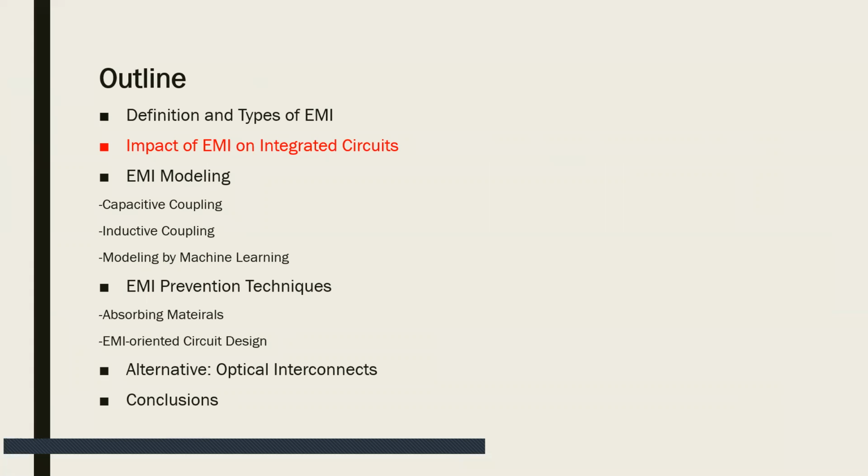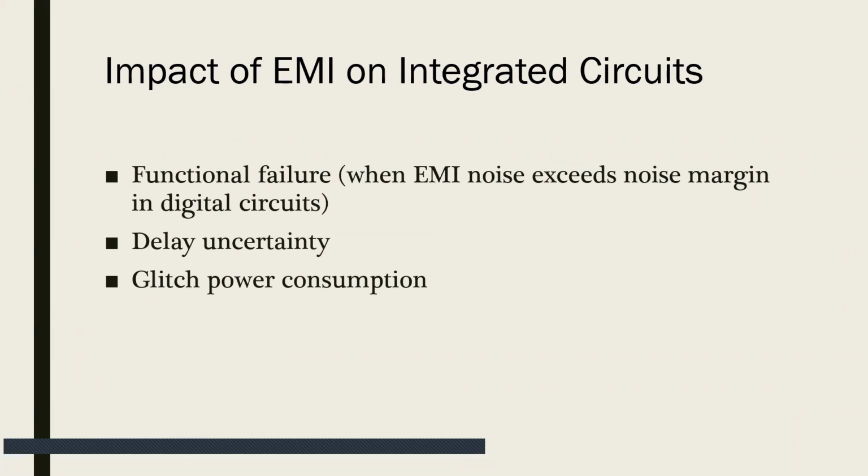And then the impact of EMI on integrated circuits. So first, it will cause functional failure in the circuit. When the EMI noise exceeds the noise margin in the digital circuit, it will cause the logic to flip and then cause some functional failure.